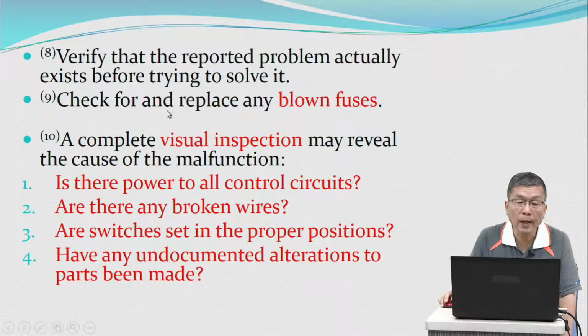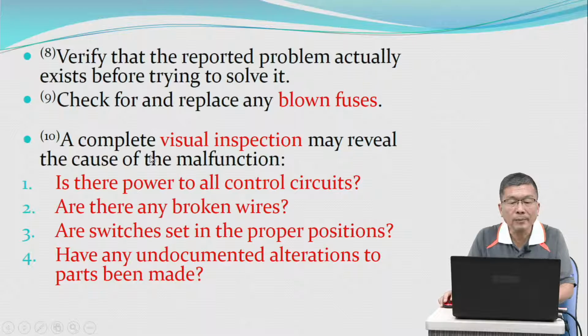Check for and replace any broken fuses. A complete visual inspection may reveal the cause of the malfunction. Is there power to all control circuits? Are there any broken wires? Are switches set in the proper position? Have any undocumented alterations to parts been made?